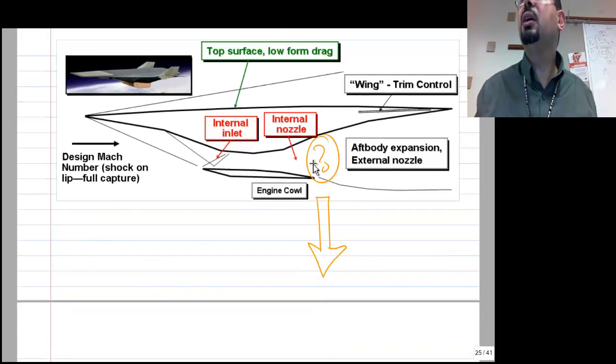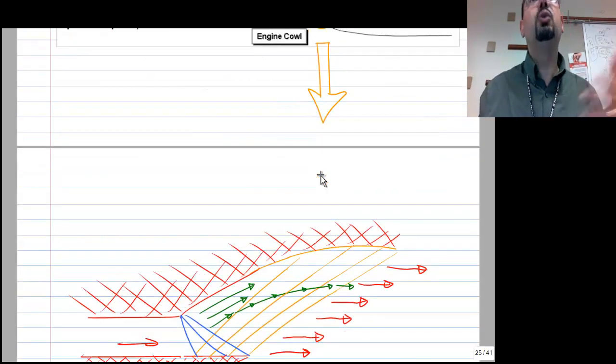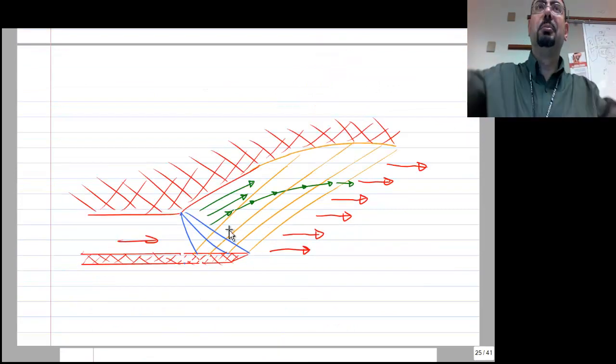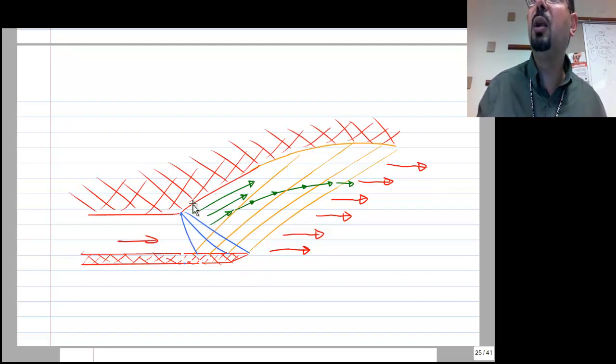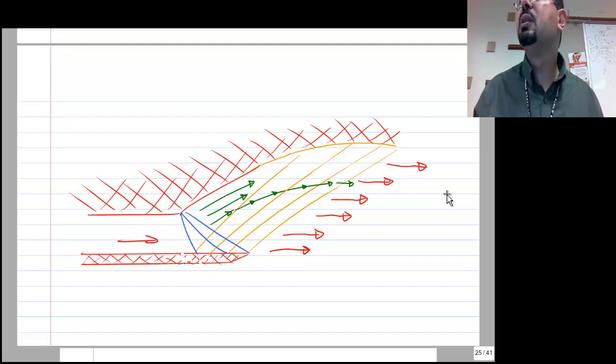So for hypersonic, this is kind of a convergent-divergent nozzle. Or basically it's a way for you to go faster. You're already supersonic, you want to make it even faster, right? So you want to speed up from, say, Mach 2 or Mach 3. How do you speed up from Mach 2? Well, if you open an expansion like this, an expansion fan will come out. The flow, rather than going horizontal, will tilt with this new wall, right? And then this expansion fan hits the floor and reflects from the floor. That reflection will make what? Make the flow straighten up again.